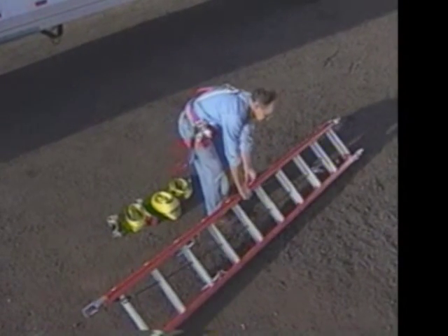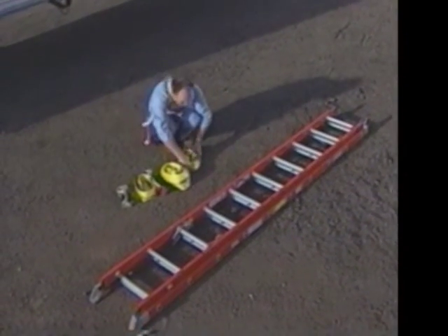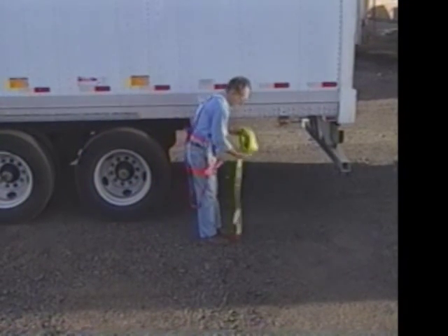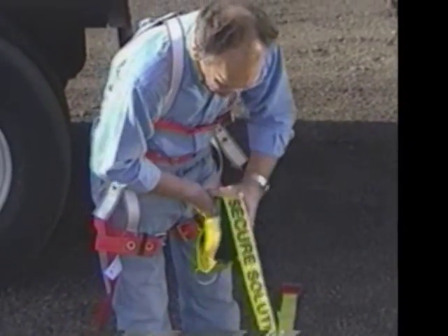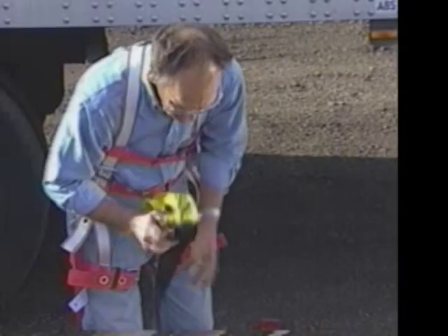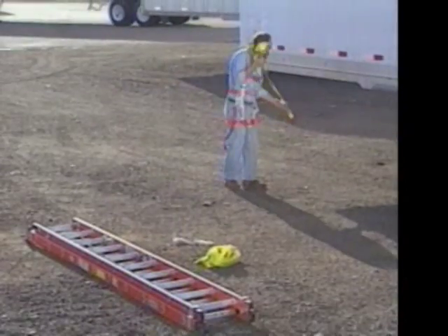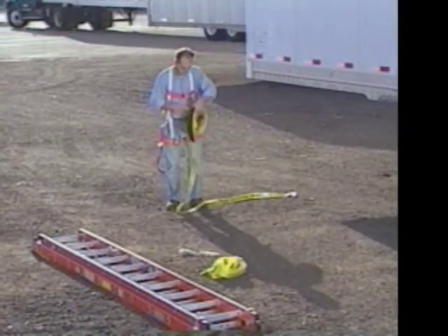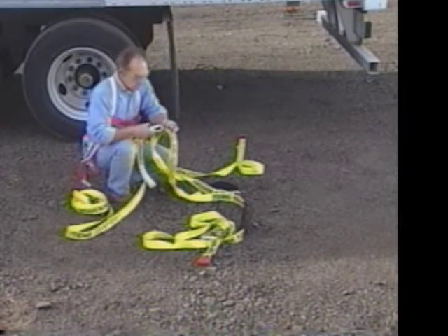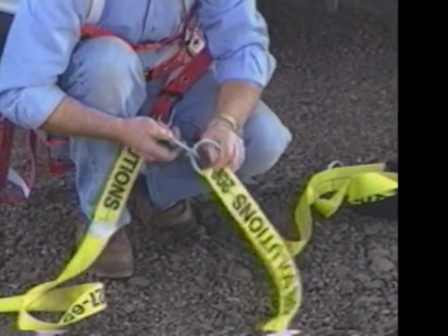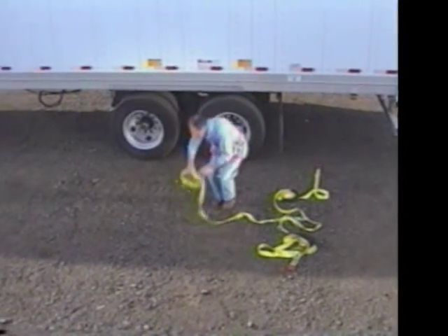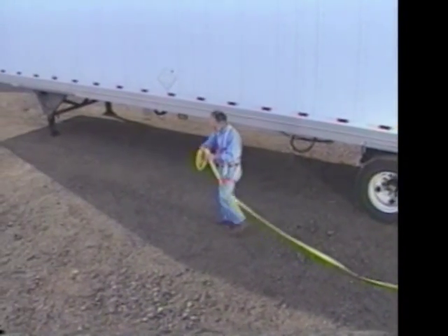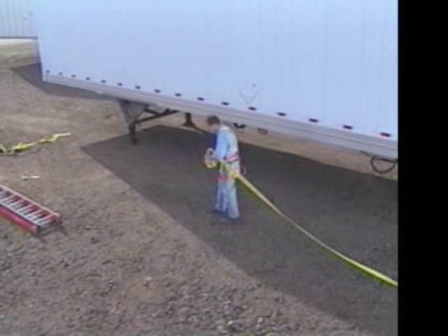You'll need a ladder tall enough to extend beyond the roof of the trailer and a tie-off to secure the ladder. As you lay out the straps, check them for tears or missing D-rings. If you find any defect, notify your supervisor and use another assembly. Position the 30-foot cross straps at each end of the trailer. Keep the flat hooks without the ratchet near the trailer. Find the center D-ring on the cross strap and snap the center strap to this D-ring. Position the 50-foot center strap along the length of the trailer.